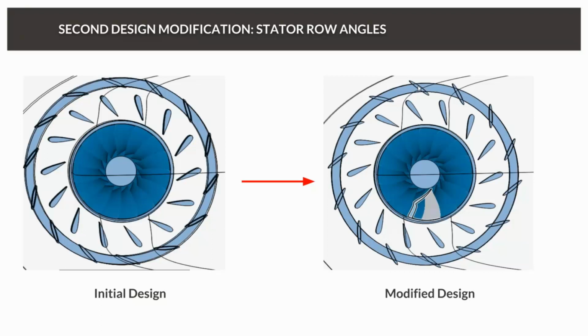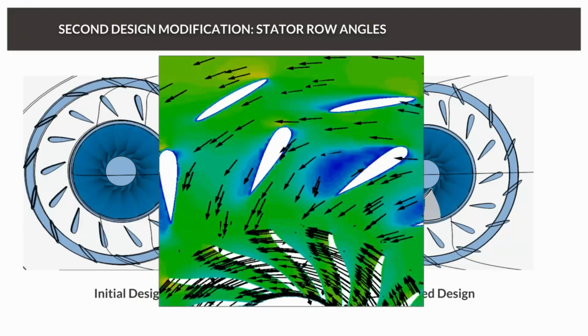Actually, what I think in hindsight is that they shouldn't even have all the same angle. Depends on how you look at it, right? So I think we could design the volute differently to control the velocity of the flow differently. Or we could not have all of these with the same angle because the velocity isn't the same all the way around. It kind of depends on how you look at it. So just to remind you, this is what we're trying to fix, this recirculation here, for example.